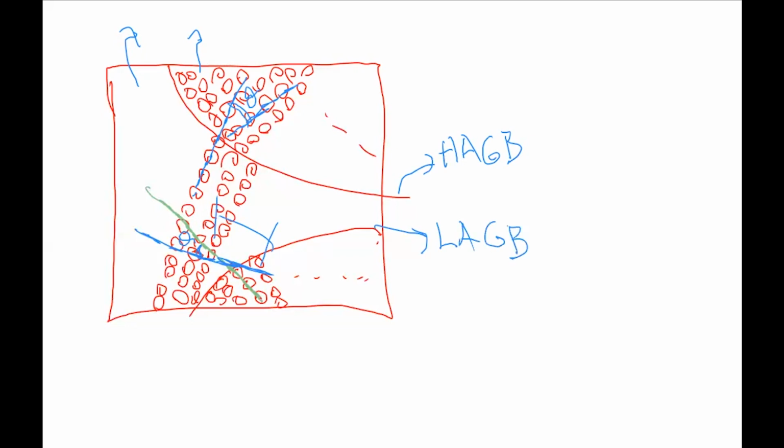And along the grain boundary, there is a disturbance in the atomic packing. So suppose this grain is also oriented this way, the same as this crystal, then we don't have any disturbance in the atomic packing. So we wouldn't have any hardening due to the disturbance.